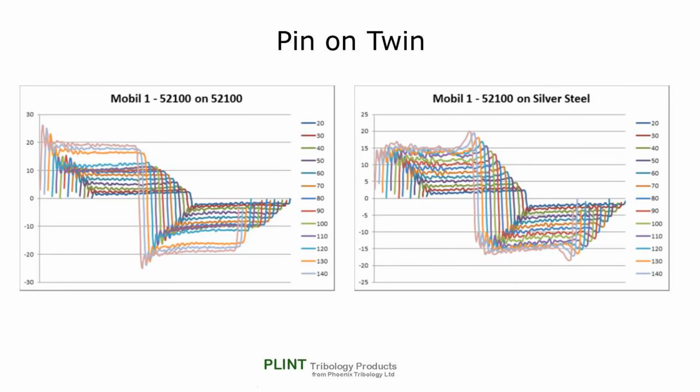The hard on hard specimens produce a well-defined spike and essentially square subsequent trace, indicating sliding over a flat unworn surface. The hard on soft specimens do not start with a spike, but end with a rise in friction. This is as a result of the specimen wear at the ends of the stroke.